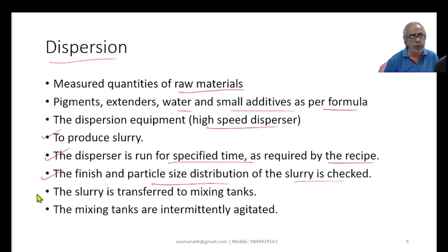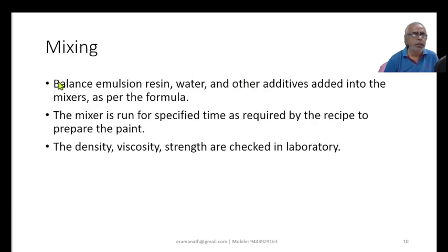Then finally the slurry is transferred to the mixing tank, and the mixing tanks are intermittently agitated and proper coloring is achieved here. Then the balance emulsion, resin, water and other additives are added into the mixer as per the formula. Then the mixer is run for specified time as required by the recipe to prepare the paint, because based on